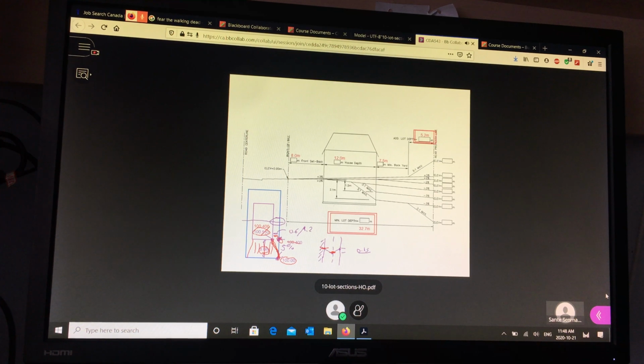If I come from the front to the corner of the house at 5%, I'm going to go down this much. What's the elevation on the side of the house in the lot corner? Yeah, I'm going to subtract 15, so this elevation becomes 100.250. Everybody with me? So now if I take, what's the slope from this point to the front?